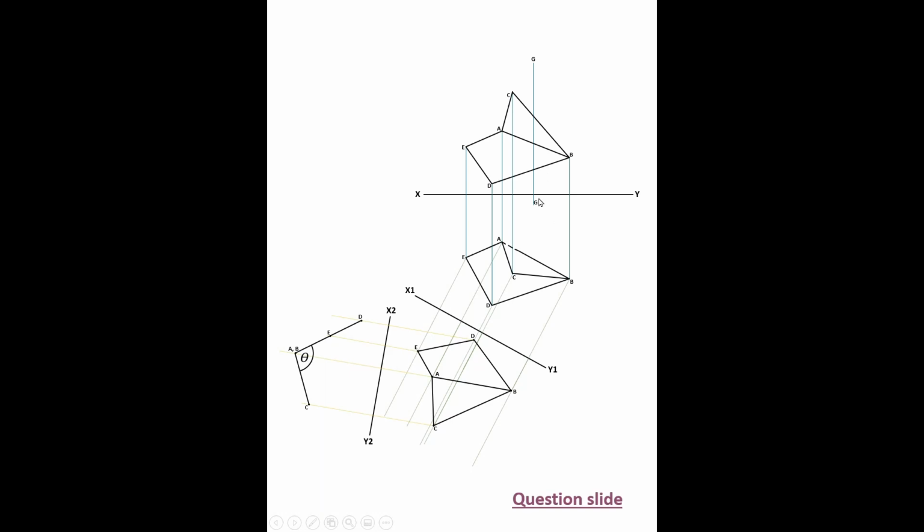So the method we use is called a rabattement. What we have to do is find GB as a horizontal line in the plan, because when it's a horizontal line in the plan, it's going to be true length in the elevation, and that's what we're trying to find. So how do we get this GB line that isn't horizontal into a horizontal position?